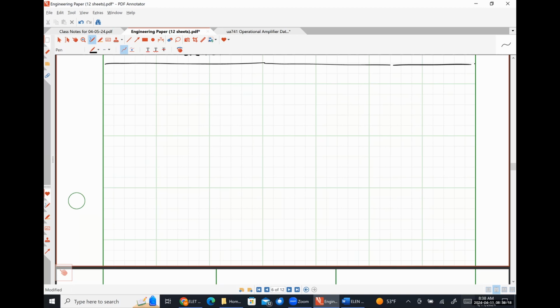Additionally, we know that our neutral conductor, regardless of what its actual impedance is, will always have a 0-volt drop over it, meaning that we can treat it like a short circuit. So we can subdivide our balanced three-phase YY network into three independent single phase equivalent circuits. Okay.